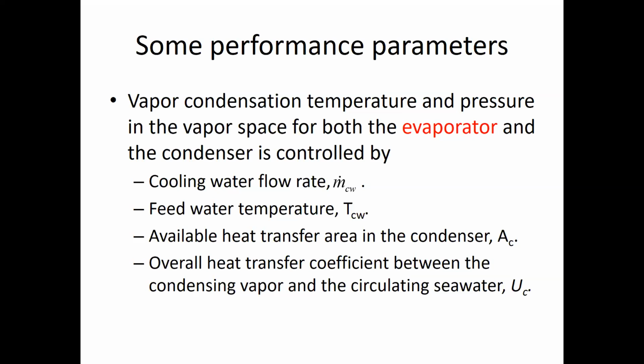So scaling, fouling is another issue. It's just a heat exchanger, and the problems of heat exchangers are basically fouling and scaling. So fouling is there. If you remember the overall heat transfer coefficient expression that you used before, right, in the heat transfer course, it used to have something that has been called fouling factor or fouling resistance.